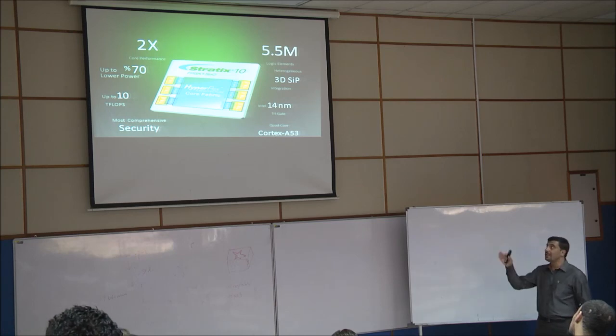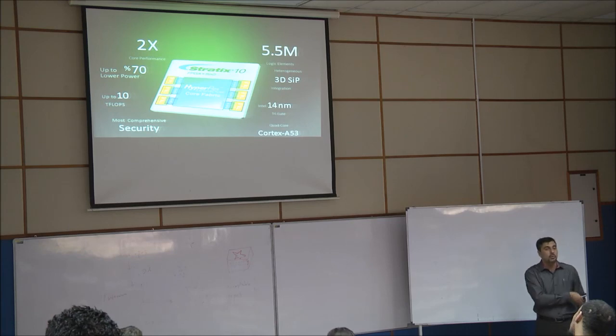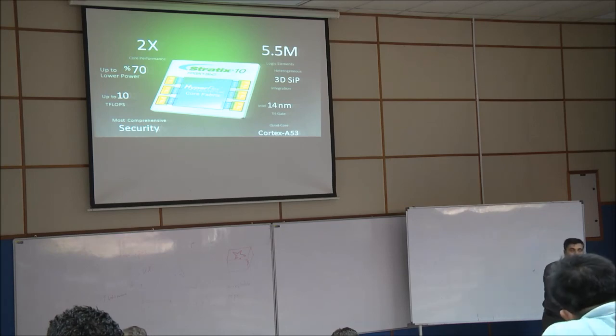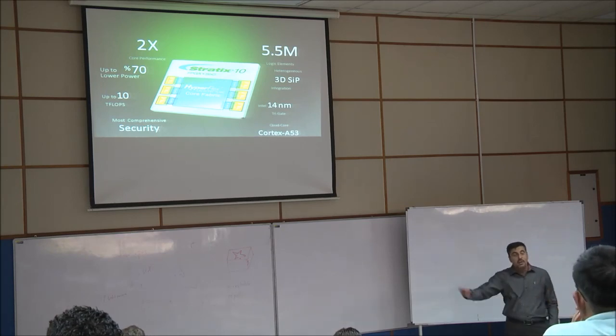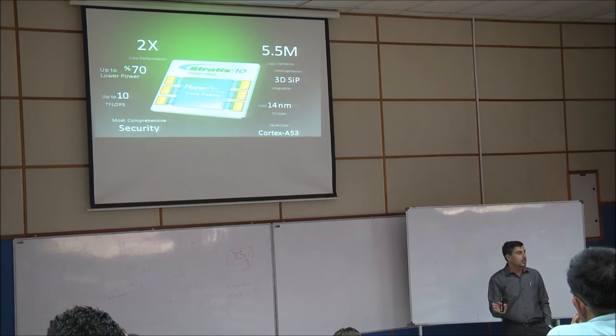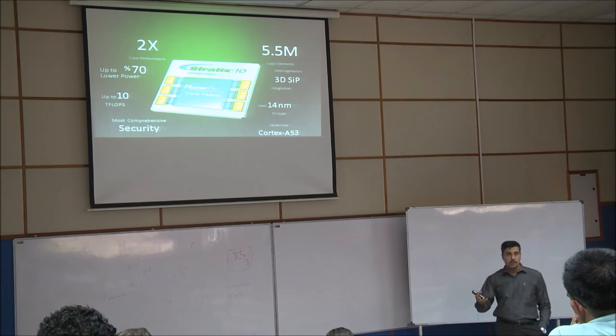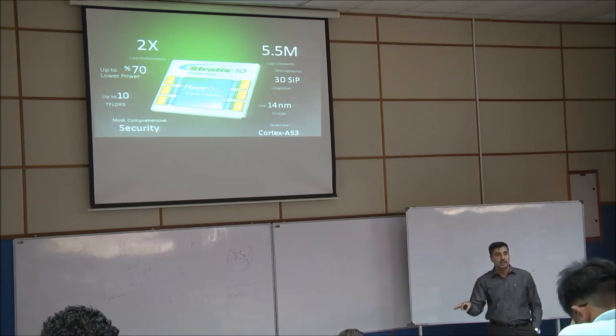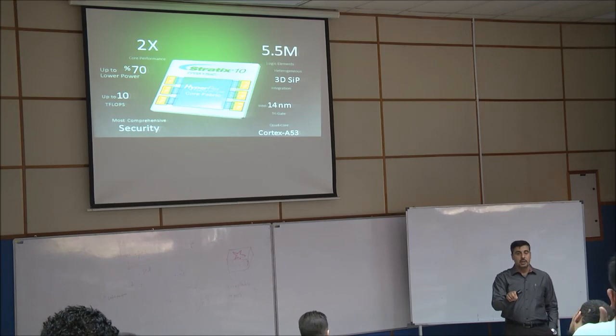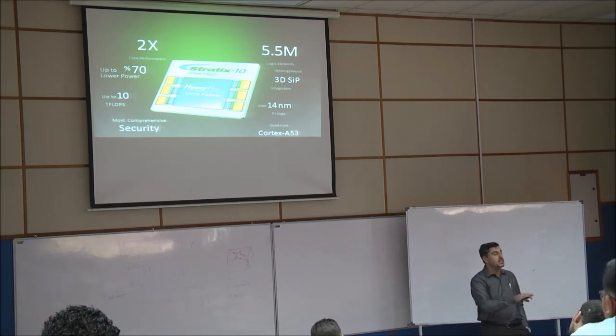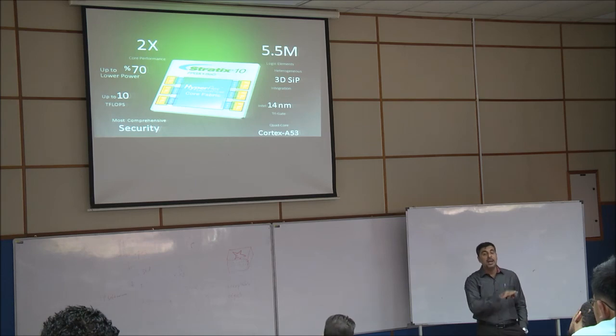Okay, it has already decreased, because normally Cyclone 2 we use on the DE2 board uses just 1.2 and 1.8 volt. Clear? Stratix 10 just uses a lower level, so it's almost green. The power is reduced. Why? Do you know why? When you compile and use your design, it utilizes only what you need. If you have pipelining inside Stratix and the pipeline is not active, it will not sit idle, so they reduce the power.